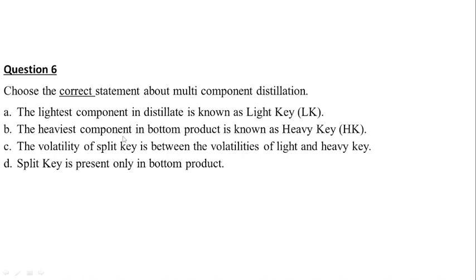Actually, the heaviest component in the distillate, the top product, is known as heavy key. And the volatility of split key is between the volatility of light key and heavy key. This is a true statement. And split key is present only in bottom product. This is also a false statement. So the correct answer will be option C.